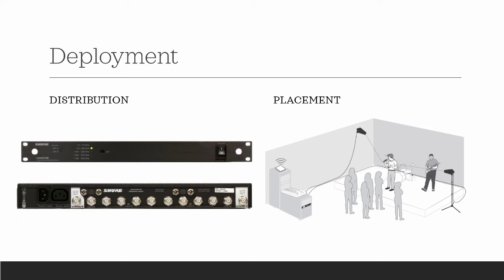With this, the next thing we want to talk about is how do we place our antennas? This is one of the biggest issues that I see when I come out and troubleshoot wireless systems, and they say, "Hey, it works really great when we're up close, but we get a bunch of people in the venue, and now we're experiencing a bunch of dropouts." In terms of setting up your antennas and the best placement, you want to have them as close to your transmit source as possible, and you want a direct line of sight between them. We're going to talk about line of sight in a little bit as well, because there are certain things that even though we can see through them, RF doesn't necessarily pass through them, but we'll get there in a second.